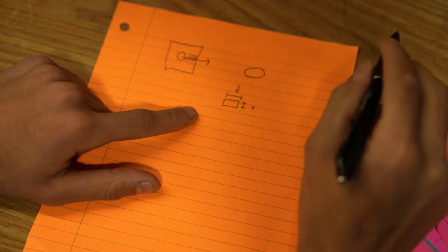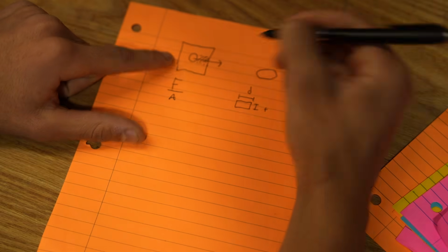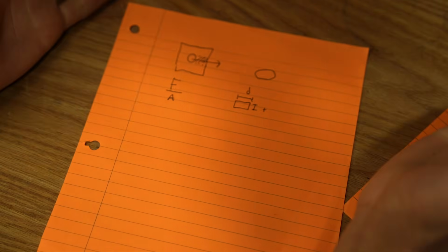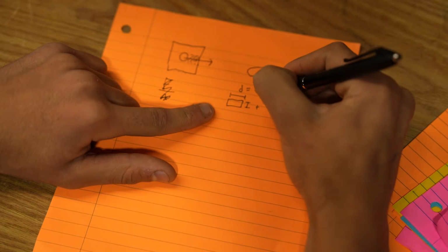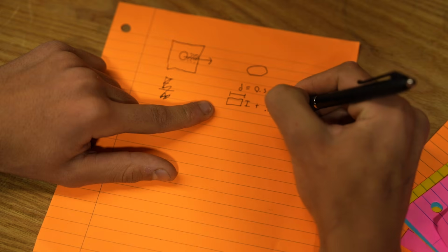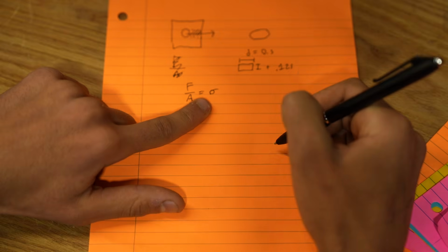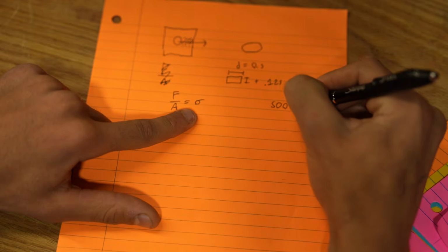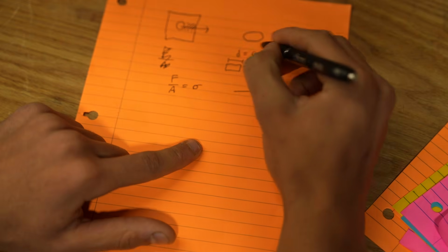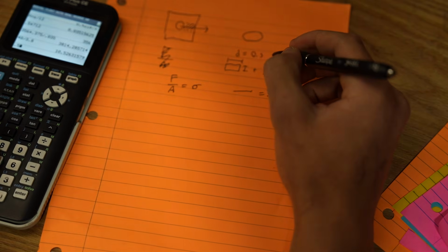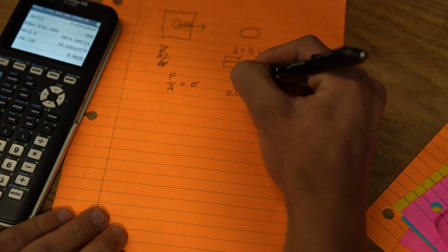And that's it. So if we do our force divided by area thing again, let's calculate the critical force for a 1/2 inch diameter fastener. D is going to be 0.5, the thickness, let's call it 1/8 inch wall, so 0.125. We have force over area equals sigma. Our bearing stress failure is going to be 50,000 psi. So 50,000 psi equals our force divided by our diameter of 0.5 times 0.125, which is 0.0625.